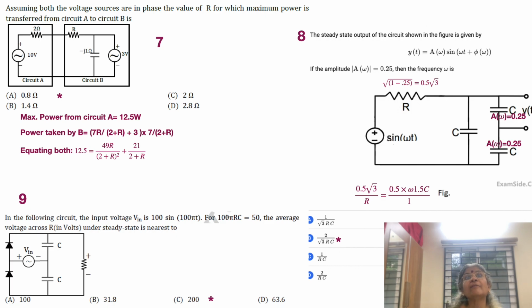Now we have a resistor, and this resistor is sharing the rest of the voltage. What is the applied voltage? It is equal to 1, because it is 1 sin omega t. So the voltage across the resistor is the square root of 1 minus 0.5 squared, since 0.25 plus 0.25 is equal to 0.5. This is obviously equal to 0.5 root 3. I suppose this is clear.